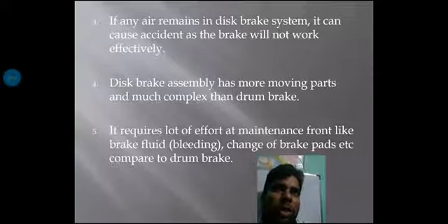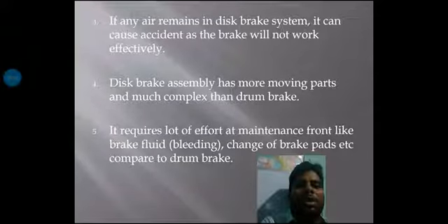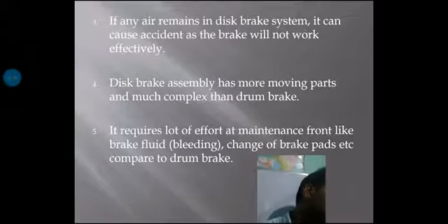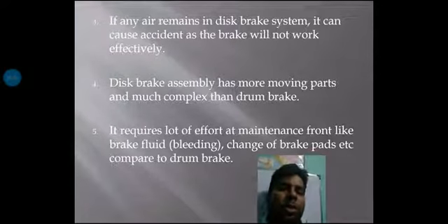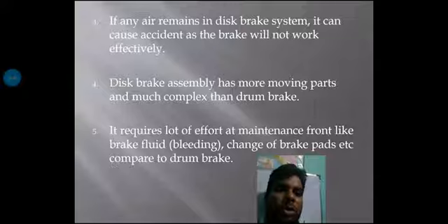From that, the total equation will come, the total torque transmitting capacity: M_t is equal to mu P R_f. Here M_t is the total torque transmitting capacity, mu is the coefficient of friction, capital P is the total force applied, and R_f is the friction radius.